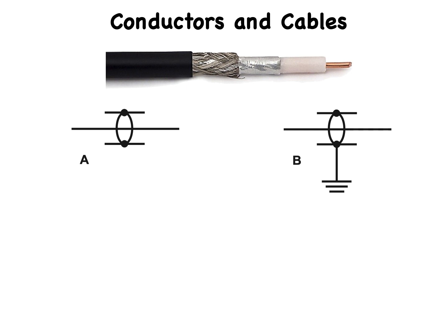Coaxial cable contains a single wire called the center conductor surrounded by a cylindrical, conduit-like conductive shield. An insulating layer, called the dielectric, keeps the 2 conductive elements isolated from each other. In most coaxial cables, the dielectric material consists of solid or foamed polyethylene.